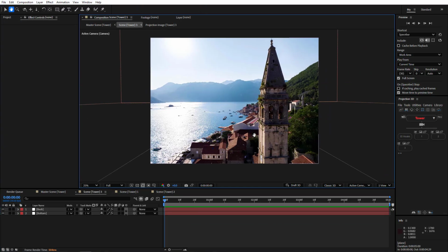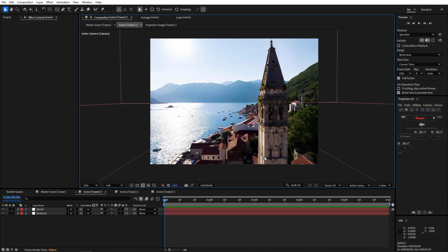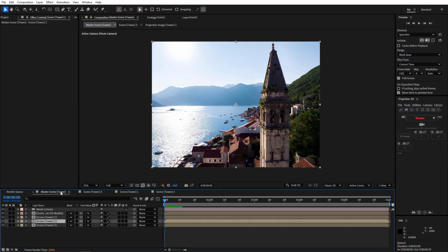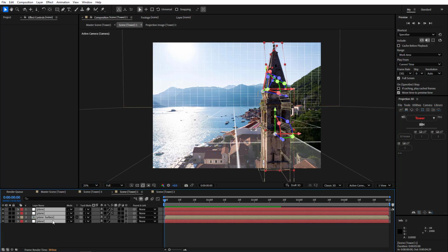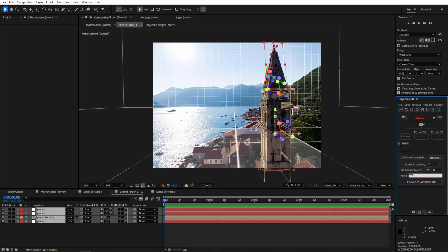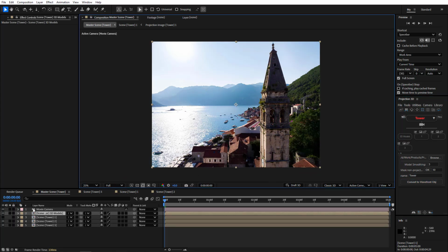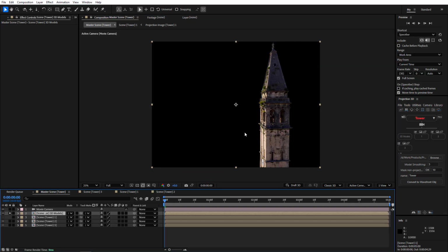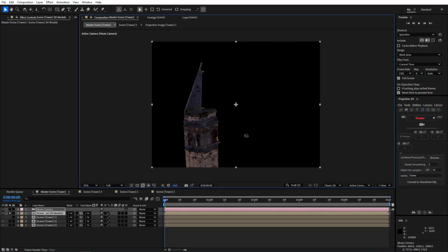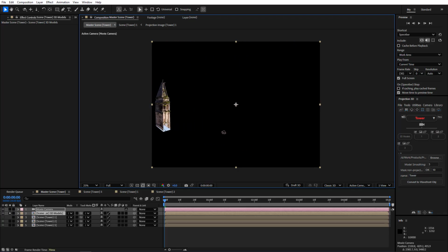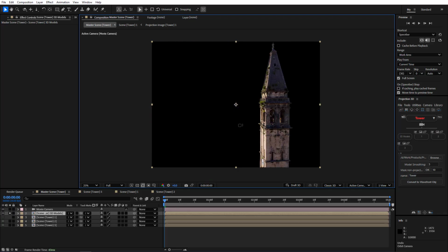All that remains here is to erase the foreground objects and restore the background behind them. And also convert all models to OBJ format, of course. Go to the first scene and select all parts of the tower model. Click on this plus sign to open 3D Object Converter. Type the name and click Convert to OBJ. Done. Let's check now. Perfect. Much faster.